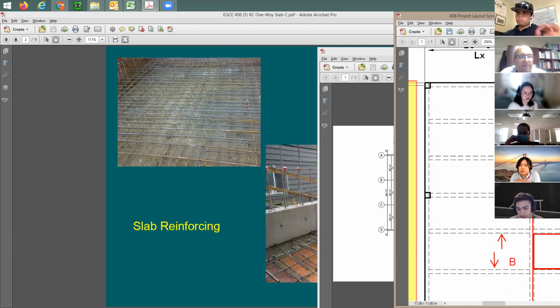Now, all of that, they support a thin concrete slab. Let's say 6-inch to 8-inch concrete slab. So actually this slab, if you like, is going to be performing in this way, because the load now would like to go from this side in the middle here. And from this side, it's going to be also coming this way. So for this specific panel, the load is going to be supported on this beam, on that beam. This is what you call here the load path.